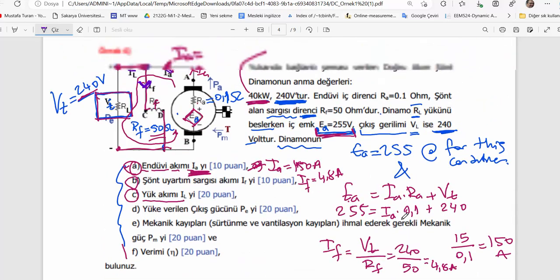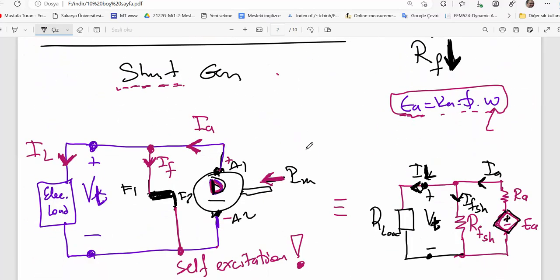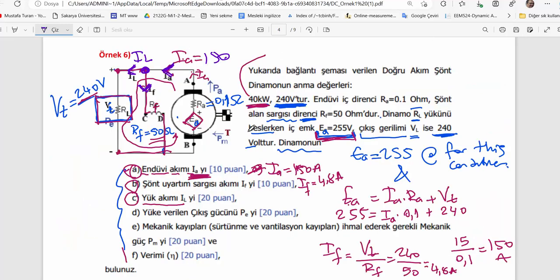As you see, it depends on the connection diagram we have already discussed here. If you cannot imagine the connection diagram, you cannot write the proper Kirchhoff's current law or Kirchhoff's voltage law. To write those relations, you should draw the proper diagram first and then the equivalent circuit. That is important, and this example emphasizes it.